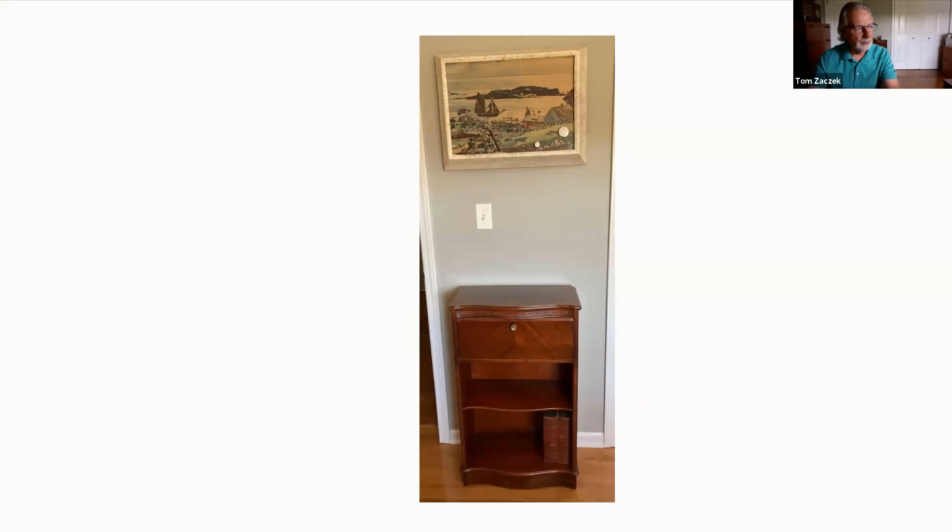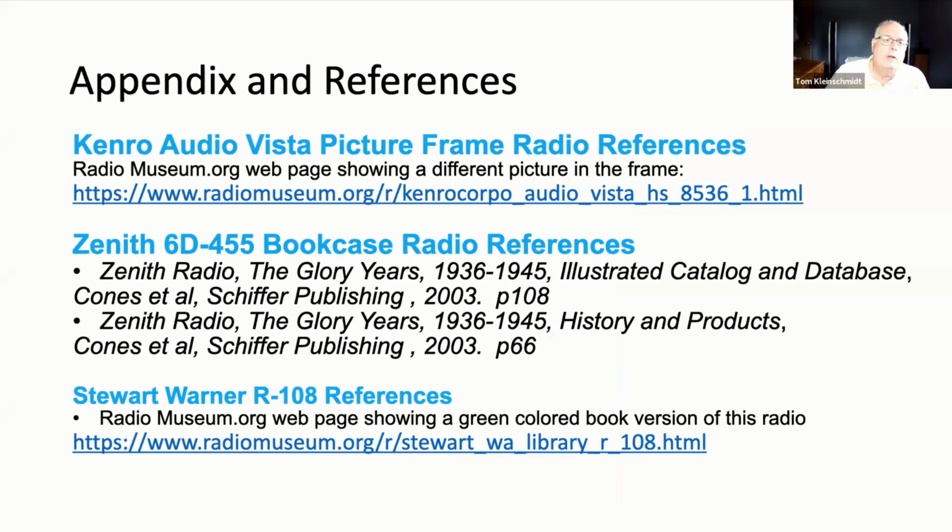And how did they get mechanical energy to the motor generator? Well, being a motor generator, the motor ran on 6 volts and the generator put out whatever it did. Dynamotor, the dynamotor would be a better word, maybe, but motor generator is the function. There's a motor and a generator, separate entities, unlike some of the stuff where it's using a common field. I think they actually have 2 separate fields. That was a Philco product on those. Packard liked Philco, so a lot of Packards were using Philco.